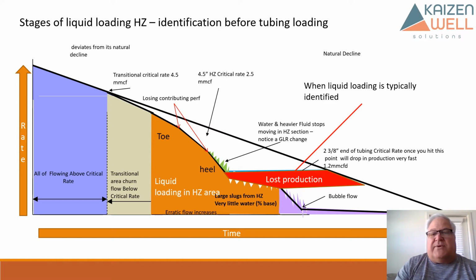So we want to react way back up here when we're starting to see liquid loading in these other parts of the well, forcing that liquid out and optimizing earlier. The difference between waiting till we're liquid loaded in the tubing and reacting to some liquid loading behind there is that we end up with lost production, which is never really recovered. So again, deferred production that is never recovered.